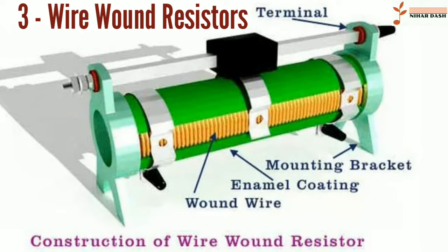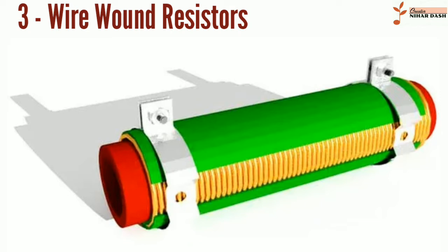If the outer case is ceramic, such resistors are sometimes described as cement resistors, though they do not actually contain any traditional cement. The aluminum case types are designed to be attached to a heat sink to dissipate the heat. The rated power is dependent on being used with a suitable heat sink, e.g., a 50 watt power rated resistor overheats at a fraction of the power dissipation if not used with a heat sink. Large wire-wound resistors may be rated for 1000 watts or more.